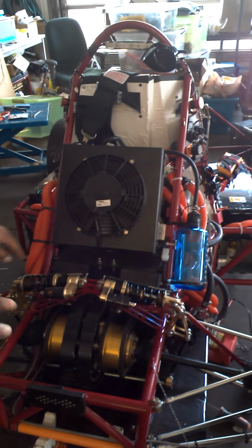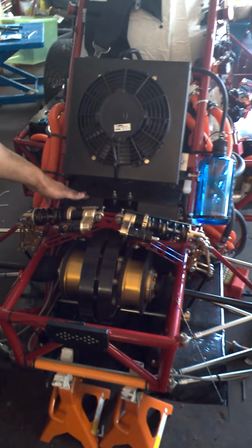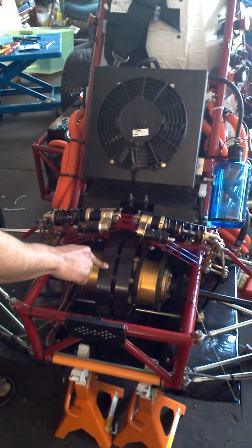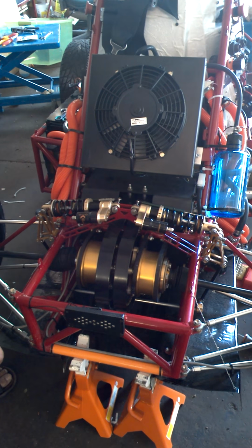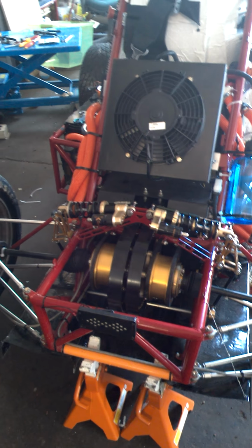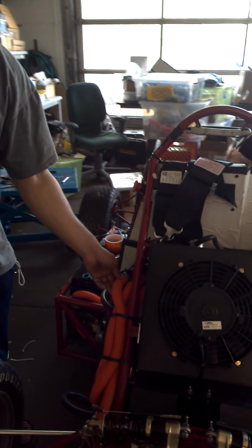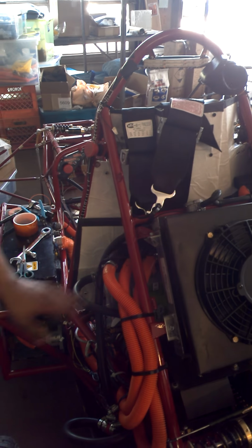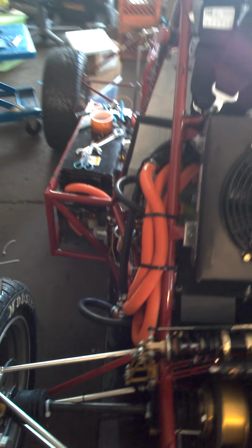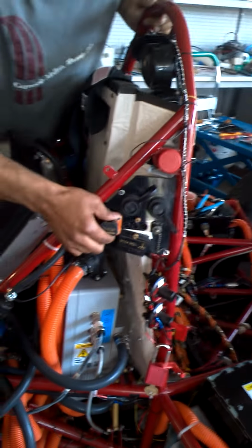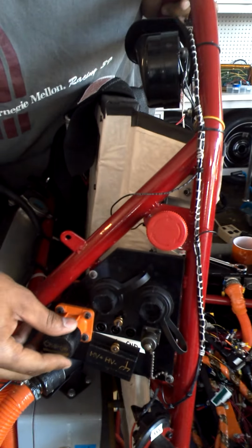The 2 motors are inside this scatter shield box for safety's sake, because the entire outside casing spins, so they're stored inside there. And it's geared down 2-to-1, so that we get more torque on the wheels. Electrically, we have 2 motor controllers as a result. They convert the DC into 3-phase AC for the motors. We have 3 wires here going into each motor, and as well we have the other motor controller. You can see there's 2 wires going into it for the DC. You can charge the car from the port right here. You can plug in a wire and charge it.